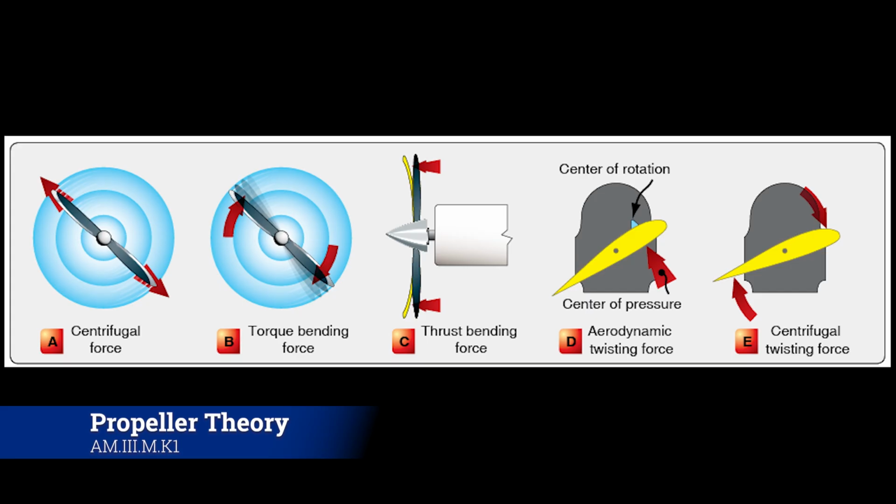So you'll see on certain propeller types towards the hub, they'll develop leaks. Those leaks are largely in part because of this, because those heavy propeller blades are constantly being slung around at thousands of RPMs, and that centrifugal force is no joke. It starts to pull on it, and over time that will wear things down. It's by far the most dominant force on the propeller. A lot of these other ones we're about to talk about happen and make a difference, but not nearly like your centrifugal force.